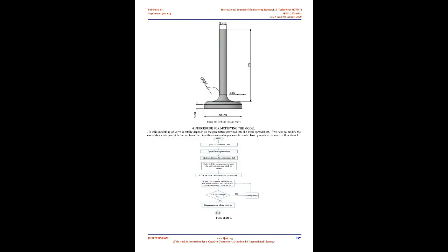In such a way the relation will get assigned to the respective valve feature. Similarly, do the same procedure one by one to relate each feature and dimension. In this way new relations have been created between every feature and the dimension from the Excel spreadsheet to the Pro/E solid part. Finally, verify the relations as per the dimensions and click on OK, which makes Excel and Pro/E completely integrated. Now save all the components set up for future reference, shown in figure 9.